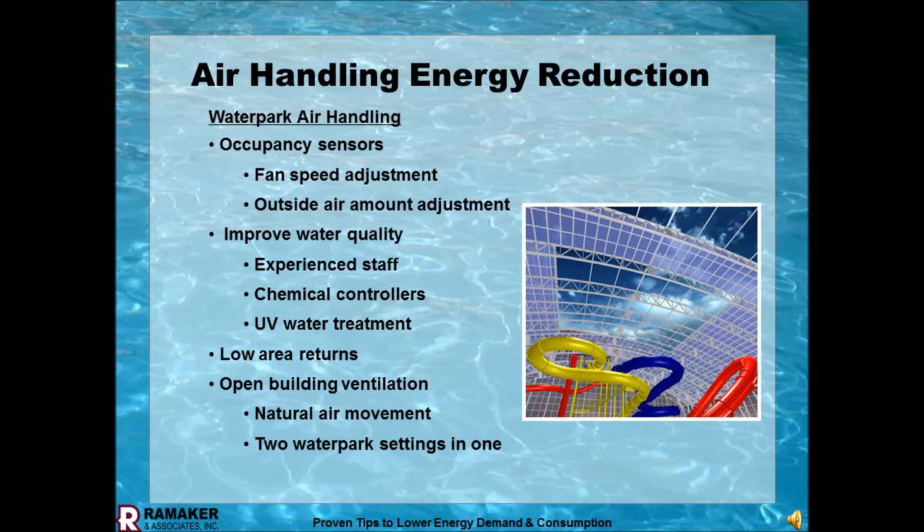Okay, I mentioned occupancy sensors for fan speed adjustment, outside air adjustment, improving the water quality, and experienced staff. Chemical controllers, please, everybody, put chemical controllers in. Don't rely on staff to do it with just test kits. And liability-wise, chemical controllers really protect you there.